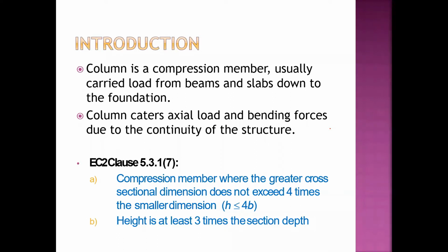What is column? Column is a compression member. So this is the keyword, compression member, which usually carries the load from the beams and slab and transfers it to the foundations. It caters the axial load and bending forces due to the continuity of the structure. By referring to clause 5.3.1 bracket 7 in Eurocode 2, column is a compression member.